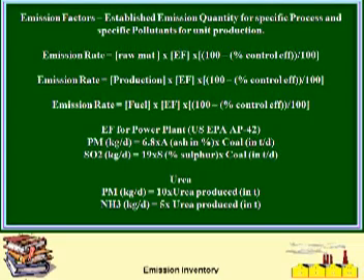Okay, so you get the emission, and then you can put the efficiency of the pollution control device that has been used by the industry, because this can vary from industry to industry, and you can find out. Emission rates could also be based on the production. The factor could be based on so many megawatts of power generated, so much carbon dioxide will be produced, because you are using a particular kind of fuel. Emission rate could be based on the fuel times the emission factor.